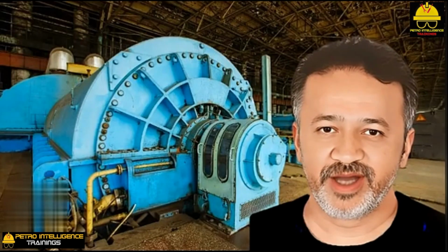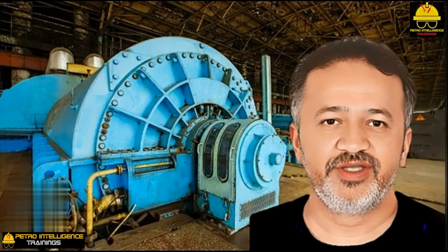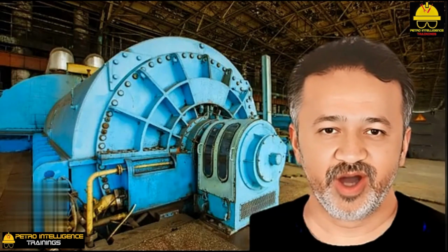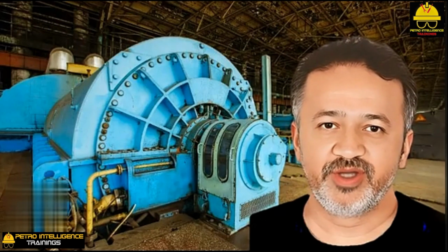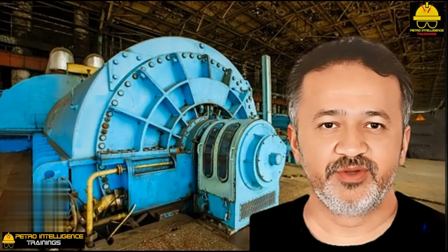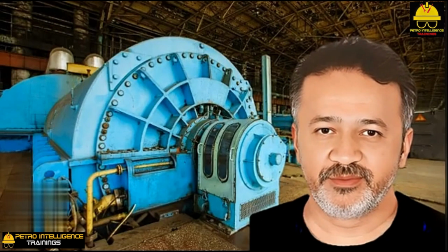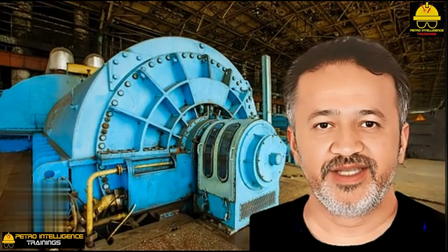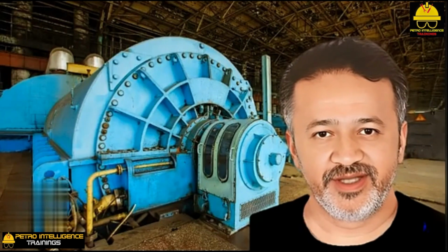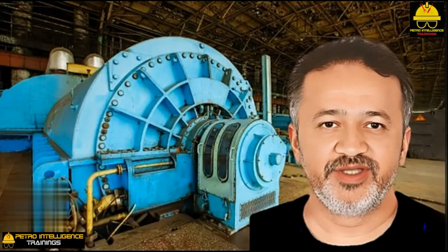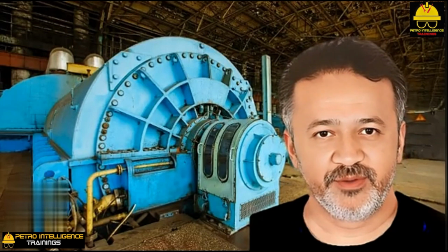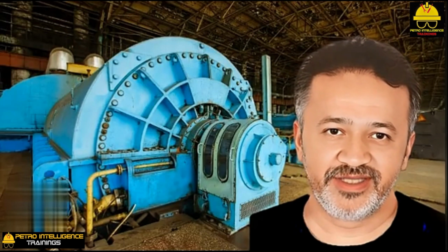Selecting optimum turbine speed. An ordinary American-type turbine is designed to run at 3,600 RPM. Its overspeed trip will cut off the motive steam flow at about 3,750 RPM. But the turbine can be run at any lower speed. There is usually a small knob on the left side of the governor valve assembly that is used to change the set speed. The question is, how do we know the best speed to operate the turbine?